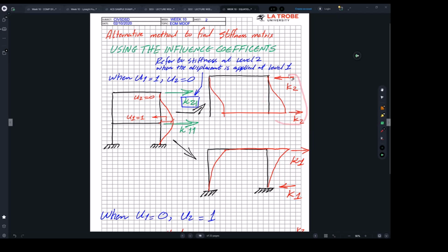So again, these have to be carefully placed based on the influence shape. So this force or this displacement has caused this shape. Then when you come to this figure, you have to show there is a K going towards the right direction, and it will be statically balanced by another K directed to the left. So you need to show the arrows as shown here.